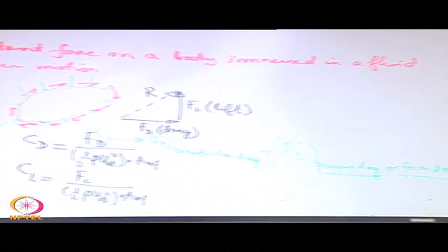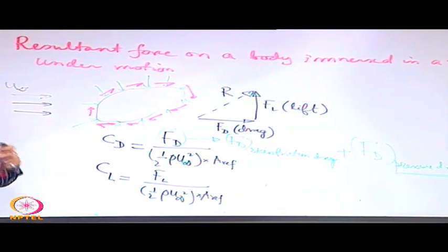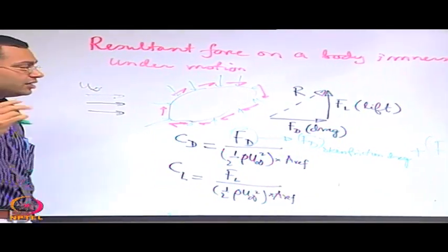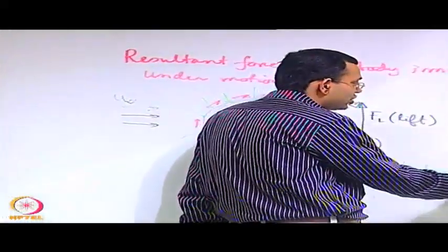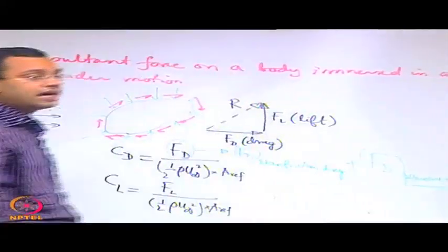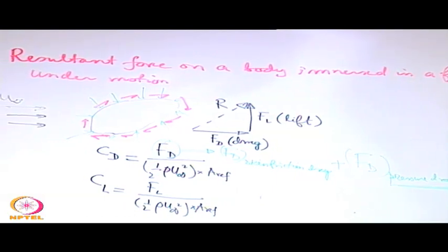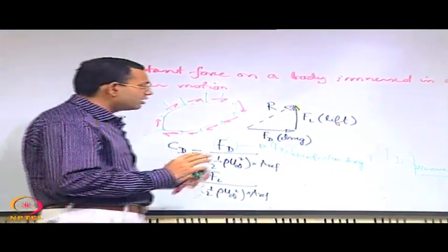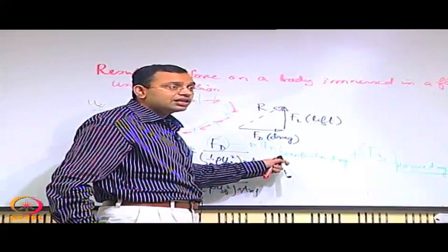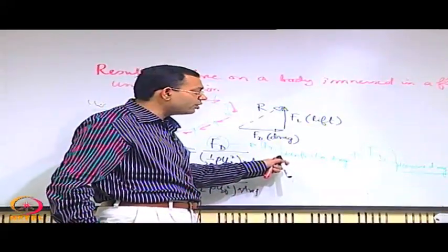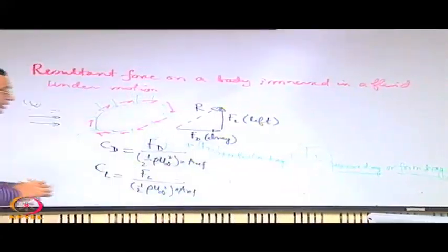In engineering, one of the important objectives may be to minimize the drag force between a fluid and a solid, and if one wants to do that, then one has to see which one is the stronger contributor, the skin friction drag or the form drag, and it all depends on whether the flow is laminar or turbulent. So, we will now look into the issue: if we consider the skin friction drag, is it greater for a laminar flow or turbulent flow? If we consider form drag or pressure drag, is it greater for turbulent flow or laminar flow? So, let us look into that.